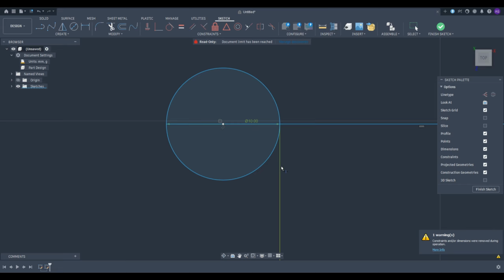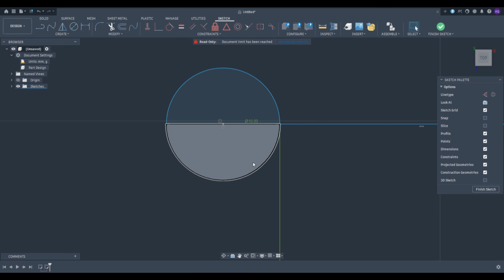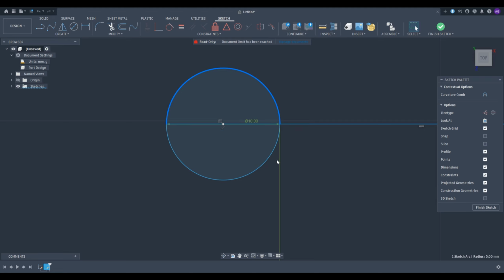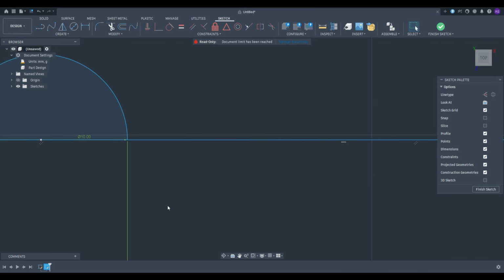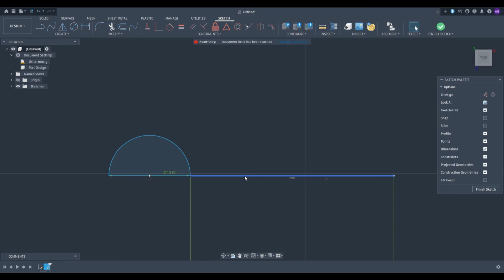Okay, it goes through, gives me some warning at the bottom, fine. And the circle's broken. So now I just hit escape to make sure I'm not in any sketch mode or selecting any lines. You just hit exit and your mouse looks normal. Now if I highlight the circle, you could see the perimeter only lights up the bottom or top half. So obviously I'm going to select the bottom and just hit delete. And now we have a semicircle and the rest of the bracket.